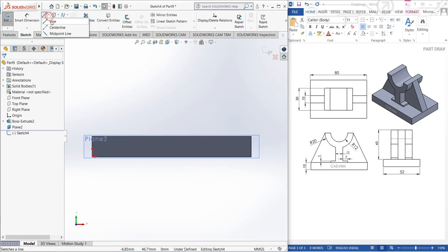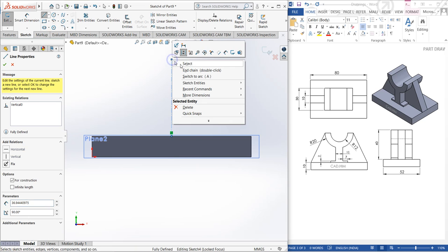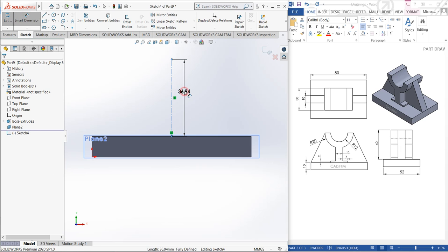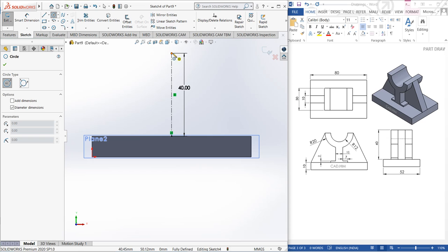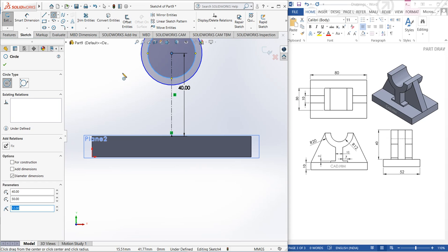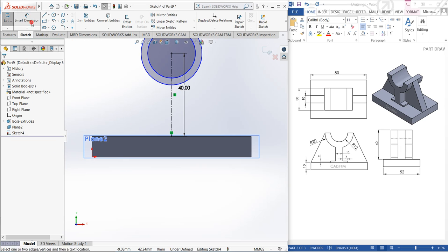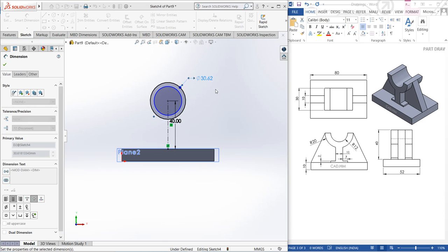Okay. Now select this front plane, click on OK. We create same loop on this body like this. Let's put it 40, right? As we already know. Draw the structure like this, one circle, and we'll just say two circle, and dimension it. This one is 40 dia.